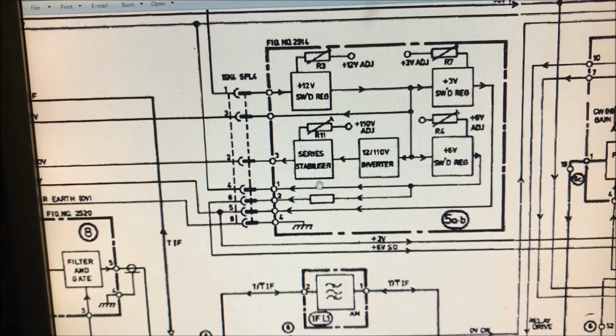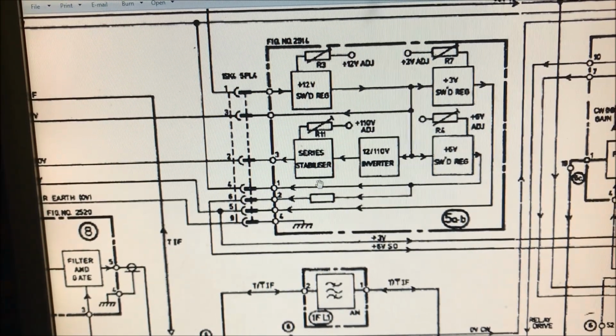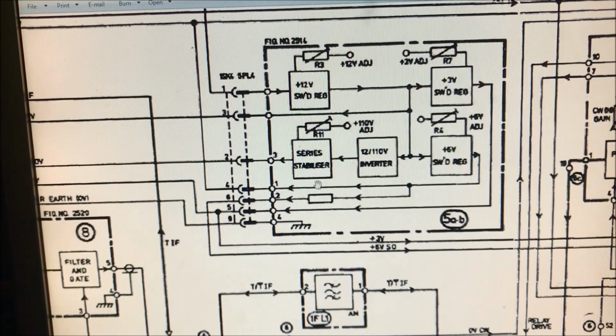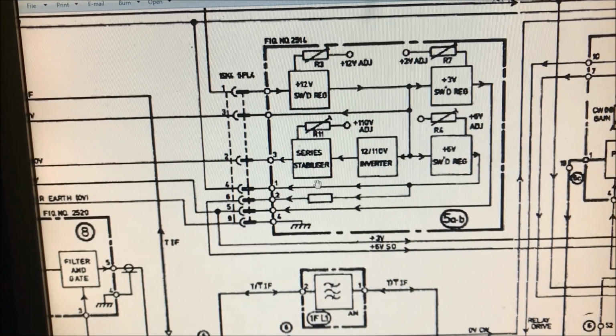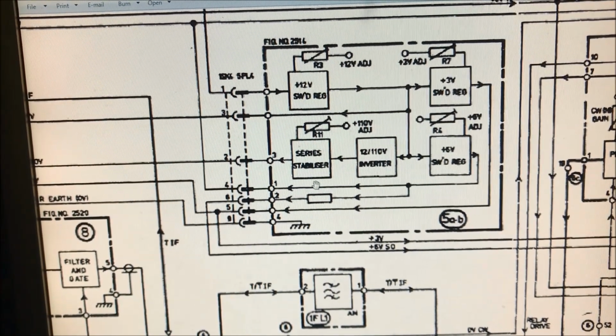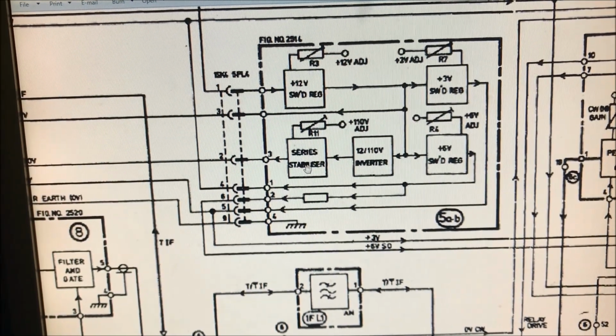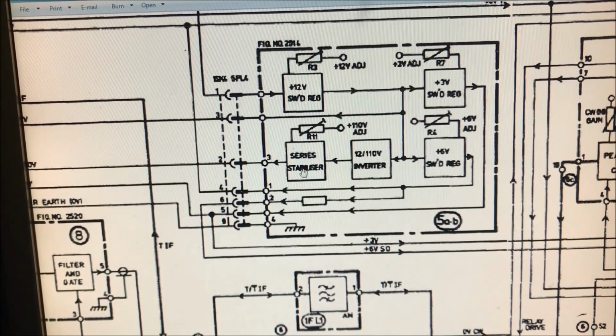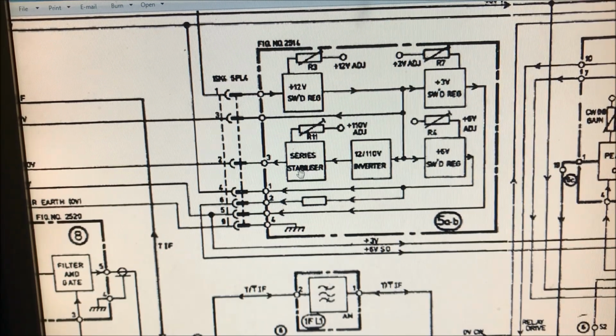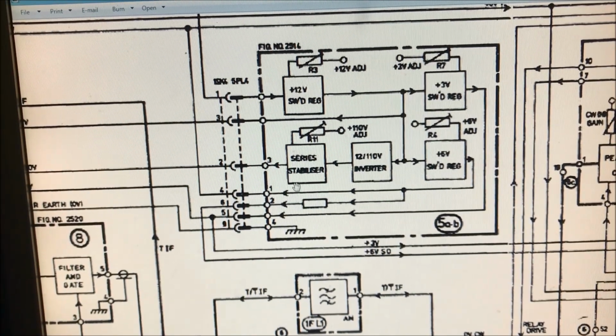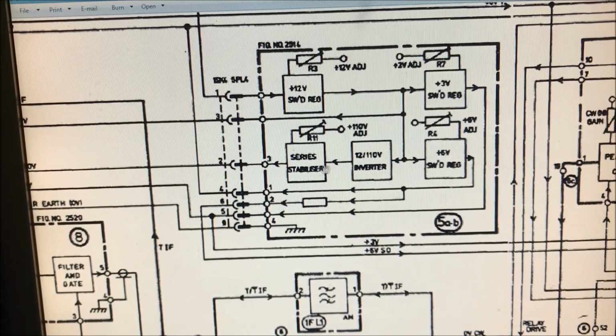I think there's C8 and C6, I think. They're the only two electrolytics or tantalum capacitors that are on the power supply. And they should be changed without saying, because age becomes weary, and weary becomes inactive. So for maintenance, simply those two capacitors are always changed, and we've all heard that 1,000 times that you need to do that.